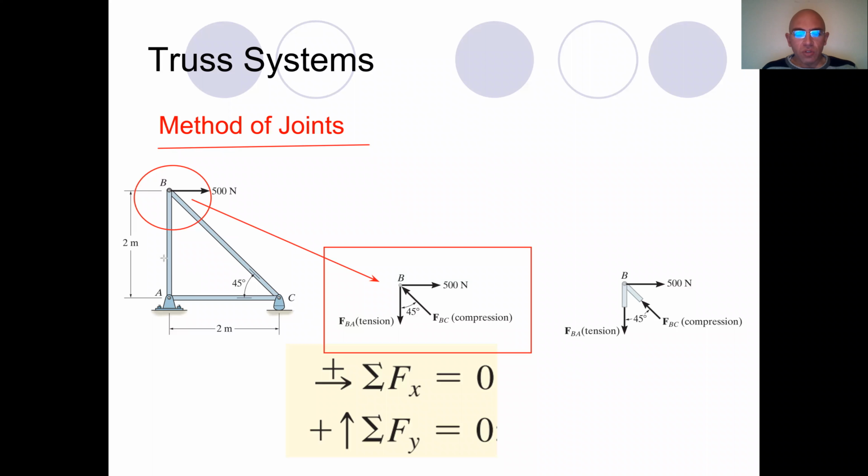So, for example, the force in the AB is in the direction of AB, or force in the AC is in the direction of the AC. It is identical in the member BC, so it is in the direction of the BC. We know the direction, but the point is we don't know the magnitude. Therefore, we can write the force equilibrium, and we know the directions. We can give the directions of the forces at point B.